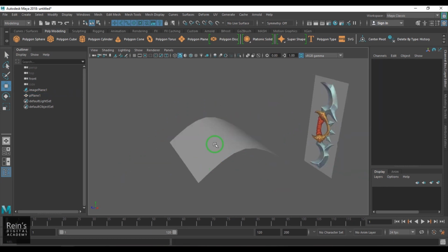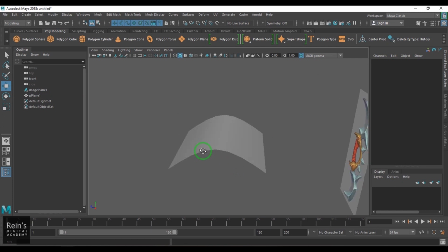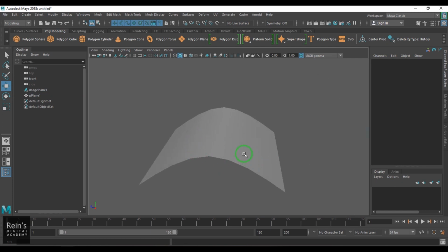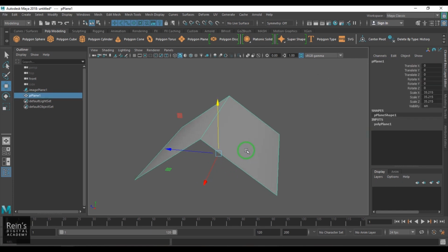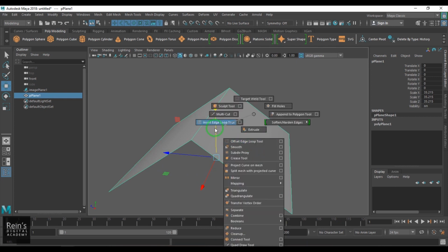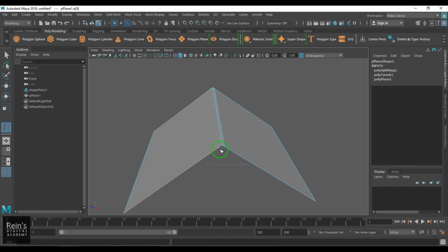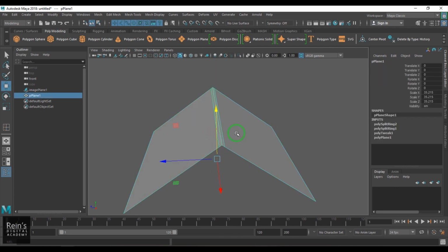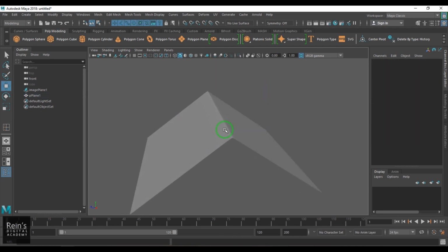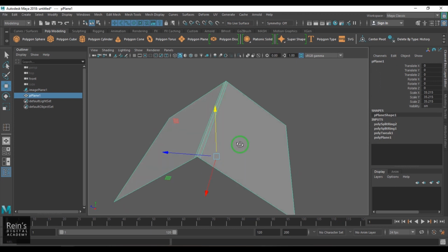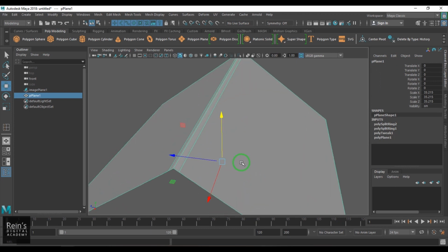So you're able to see that gave me a round corner. It has not given the crease. So what we generally do is insert an edge loop on both the corners like that, and when we apply the smooth it gives me the sharp corner. So whenever you are creating a crease, these 3 lines are important.